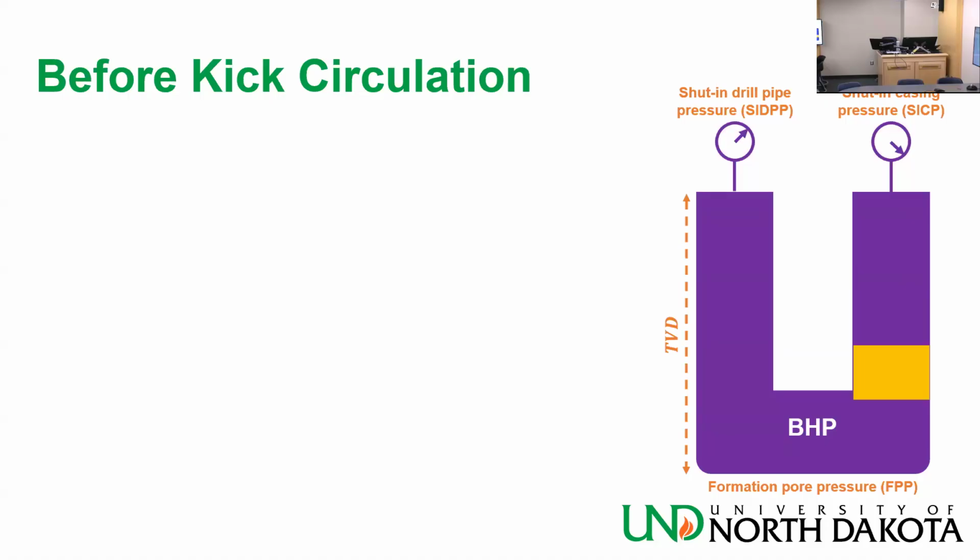No, I'm looking at the annulus. It's the SIDPP value, but I'm looking at it on the annulus side. So the SICP becoming lower than the SIDPP. I'm getting there. I'm at 530, and I know at 500 I'm going to get more kick. Based on what operations I have in my hands, what can I do to avoid that? To make the pressure go higher, the pressure that I control, the SICP.